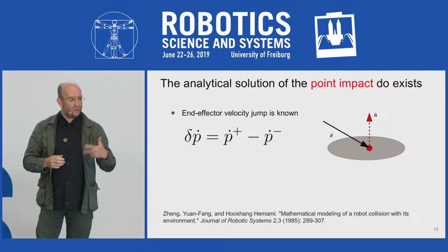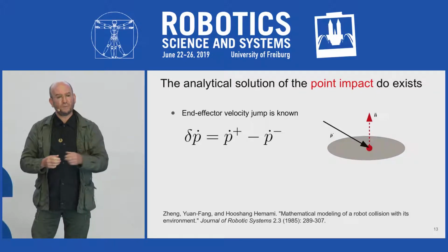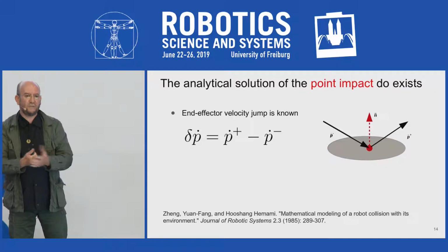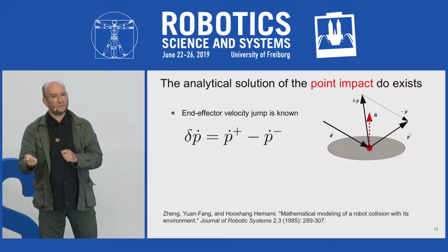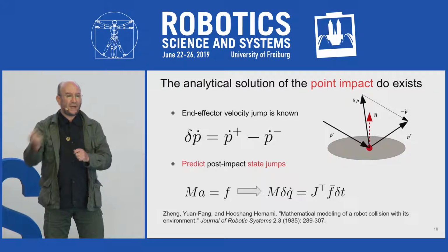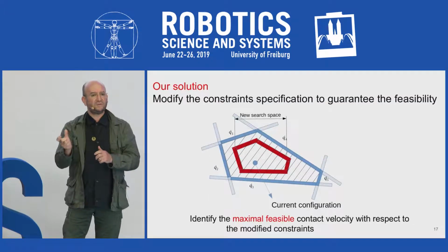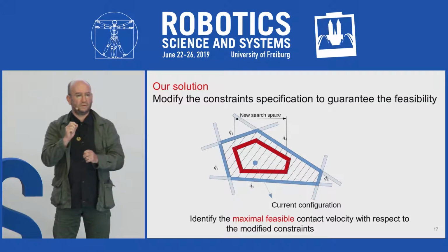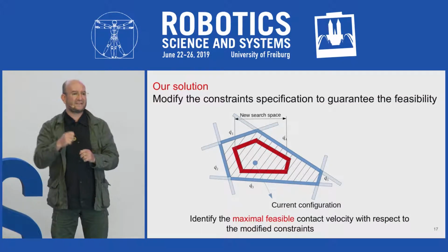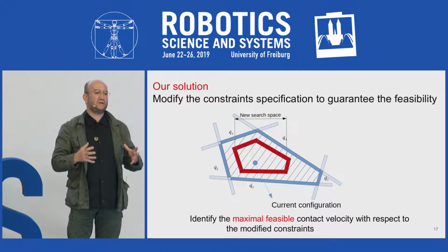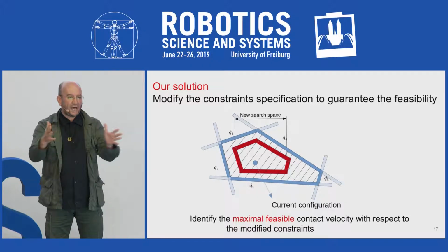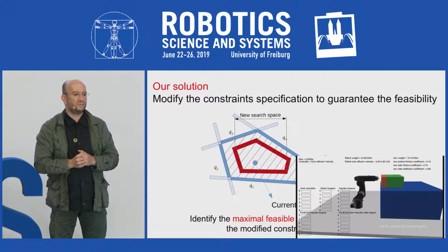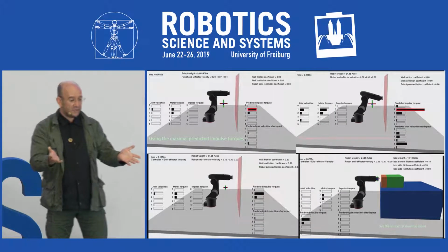Since we don't have reliable 3D models for impact, we are using a point impact, and we have point contacts anyway. So then we took point impacts, and then we compute the velocity after impact, and we integrate the difference between the velocity after impact and the current velocity as a decision variable in the QP. And then we say, OK, compute the acceleration of the motion, assuming that you will have these margins, okay, of jump in the velocity. Then things behave nicely.